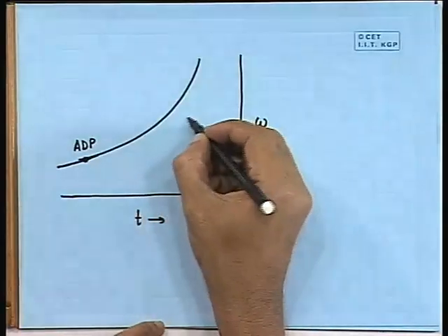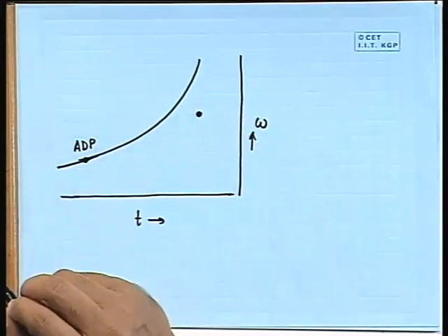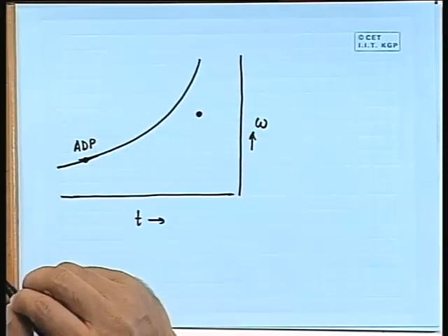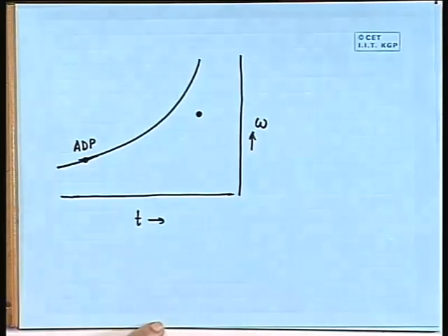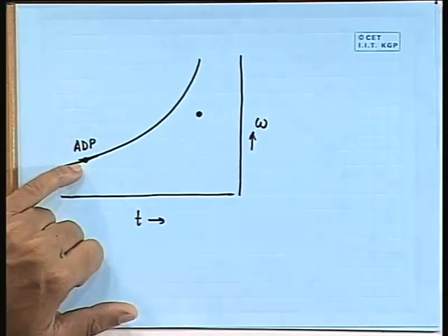Is it not? I have explained apparatus dew point temperature. You see, the ambient air is somewhere here, and apparatus dew point temperature is somewhere here, because at this condition if air comes, it will be saturated and its temperature will also be low enough.